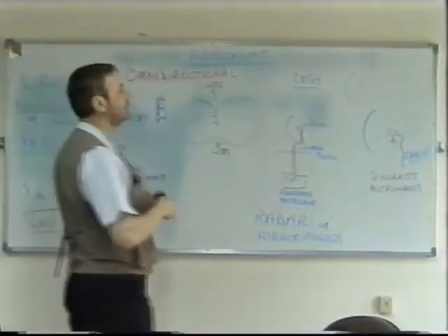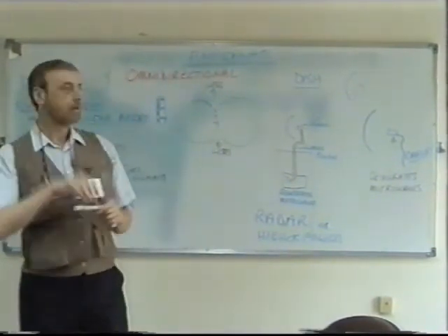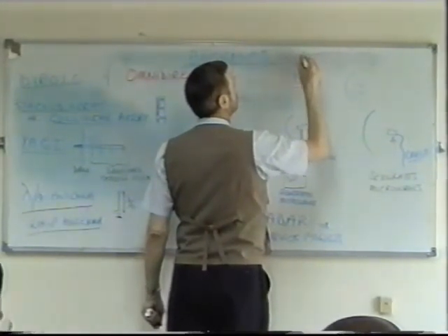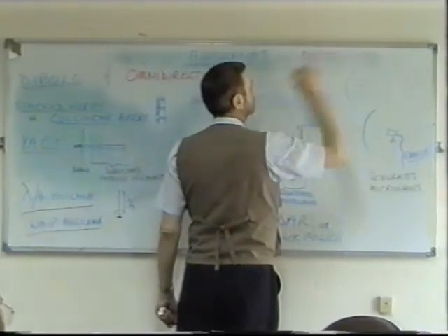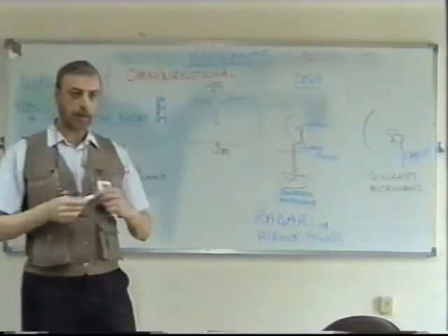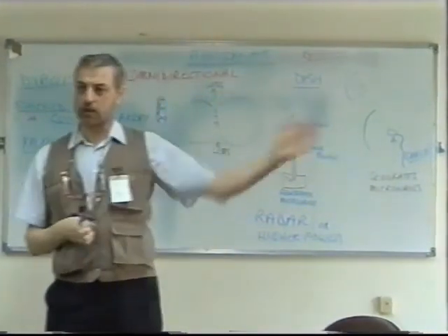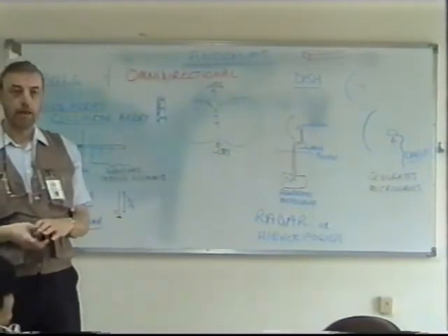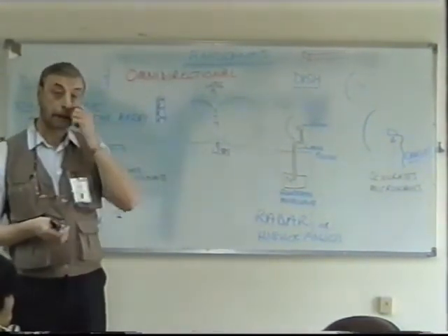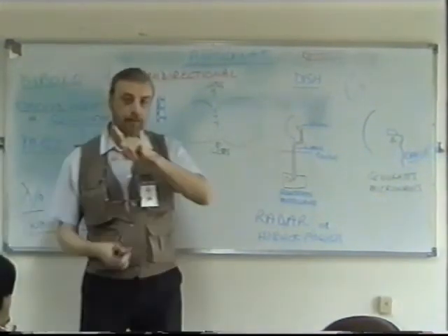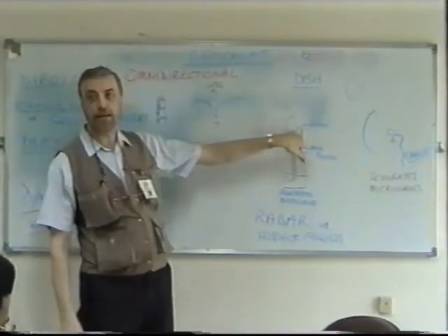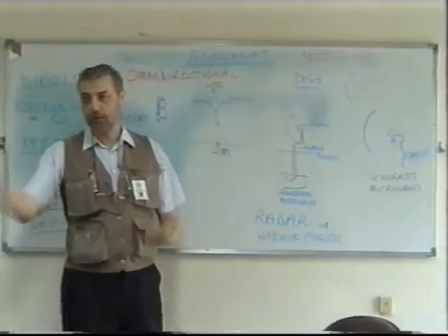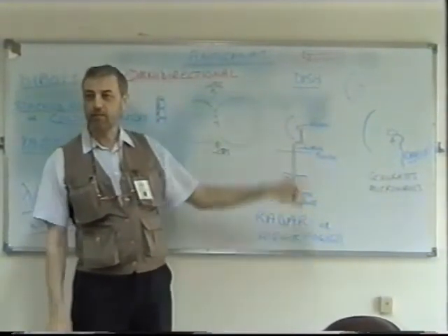Now the pipe can be round, or the waveguide can either be like this. Maybe only military use this. Military could use it. I've seen it on ships. I used to work on ships as a radio officer, and one of my jobs was to maintain the radar. And the radar on a ship sometimes used the waveguide system. The reason for that is that if we put the electronics here on a ship, you get a lot of seawater and the wind and the weather and everything, more likely to be damaged.